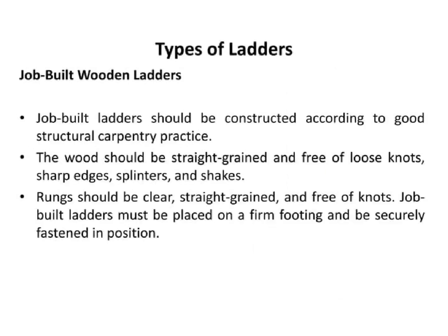Wooden ladders that are job-built require good structural carpentry practices to be used during construction. The wood should be straight-grained and free of knots, sharp edges, splinters, and shakes. When building the ladder, the rungs must be straight-grained and also knot-free. To ensure maximum safety, it is essential to put the ladder on a secure footing and firmly secure it in place.